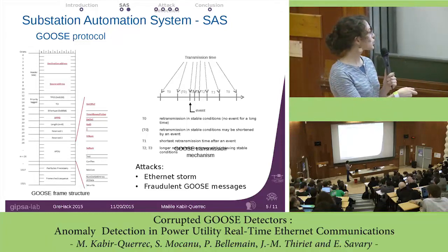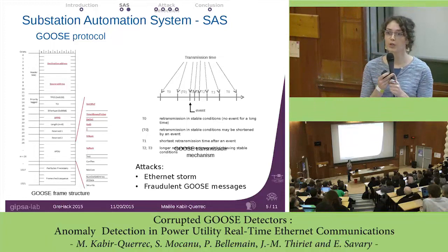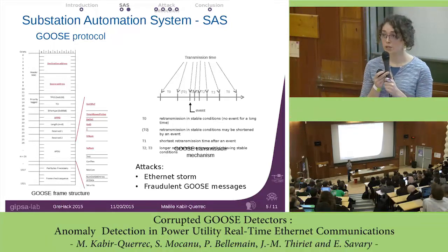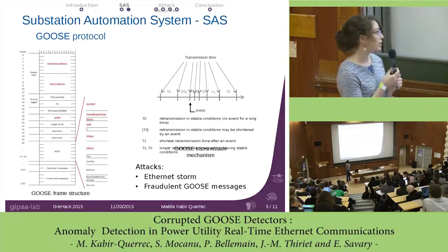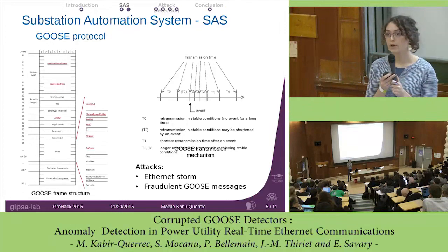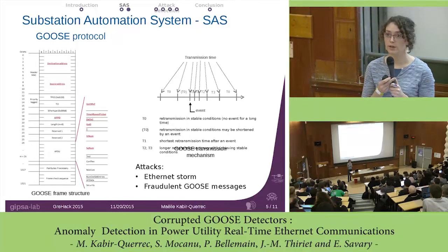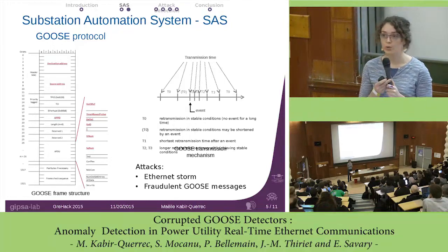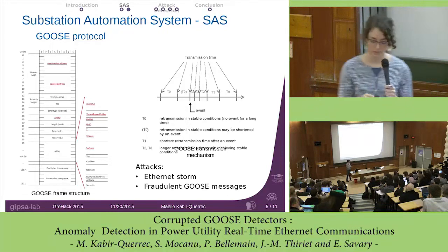I must mention also the security field, which is defined in the standard, but the standard doesn't give any further explanation about the use we must make of it. And actually, for instance, the IEDs we have on our experimental platform, Siemens SIPROTEC 5 line, do not use this security field.